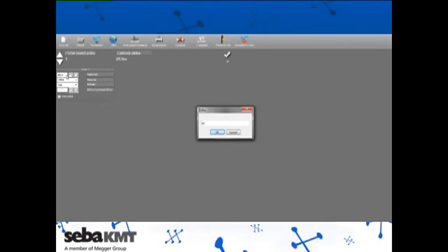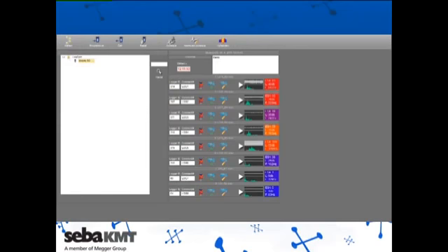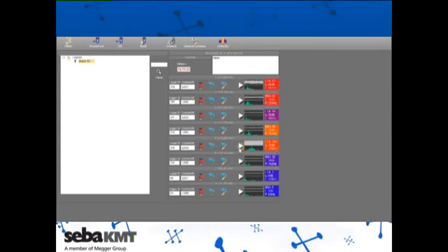After downloading the measured data from the loggers, we initially get an overview representation of all sensor data. By means of the graphical signal representation as well as the numerical values, we can see the most significant leak noise at loggers number 5 and number 1.